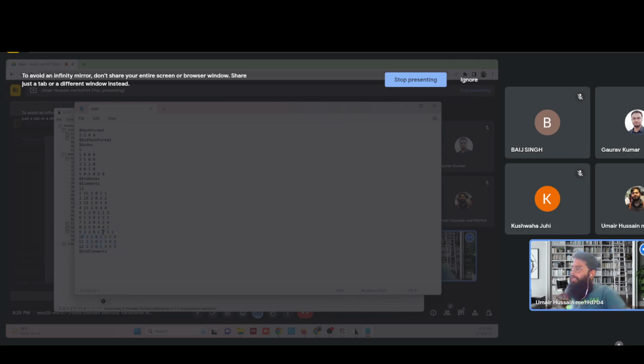The last three columns of each 2 row are your connectivity matrix: 2 5 1. I think five is your middle node, so five will come everywhere. 2 5 1, 1 5 4, 3 5 2, 4 5 3. So this is how you create a mesh file.